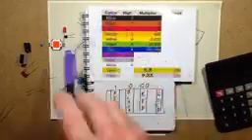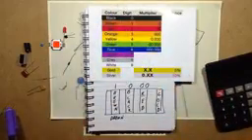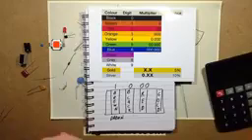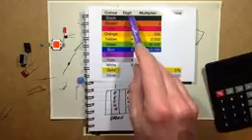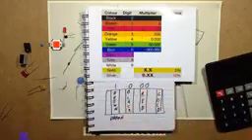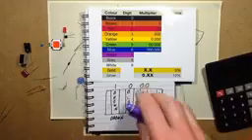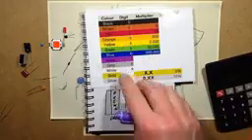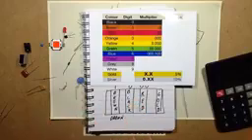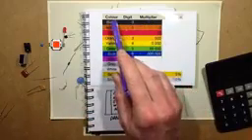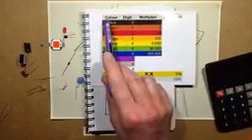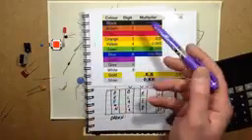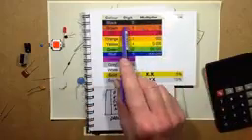So there are ways to remember this. The one I was taught with is Billy Brown revives on your gin but values good whiskey. That's basically the first letter of the colours in sequence, starting at 0 and going up to 9. This is one of these things that seems a bit daunting when you have to remember a colour code like this, but the more you do it, the easier it gets. And there are really rude ones. It's helpful when the first word is actually the colour, but the first two letters are B, unfortunately. So Billy Brown, the Brown indicates the brown colour.